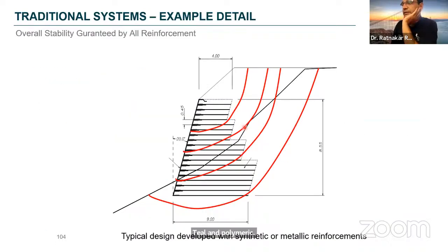When you design these mixed reinforced soil walls, you may design considering the overall stability and internal stability. If you use only polymeric layers, you will need a polymeric reinforcement in every layer, okay, and check the design.